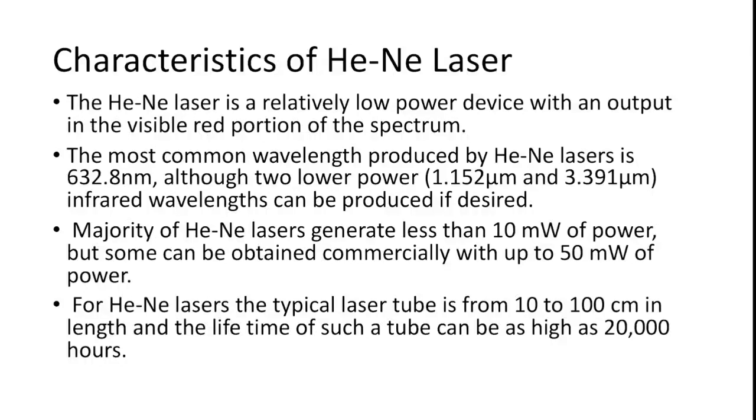To obtain single wavelength laser light, the other two wavelengths of laser need suppression, which is done by many techniques and devices. So it requires extra technical skill and increases the cost also. High voltage requirement can be considered its disadvantage. Escaping of gas from the laser plasma tube is also its disadvantage.